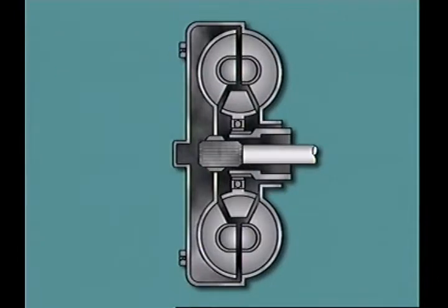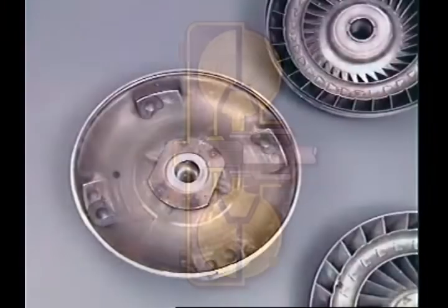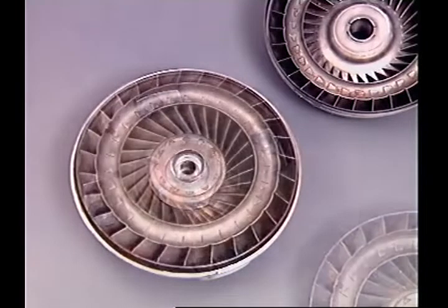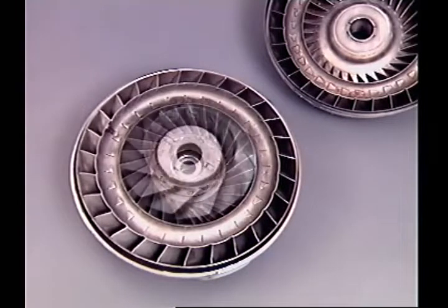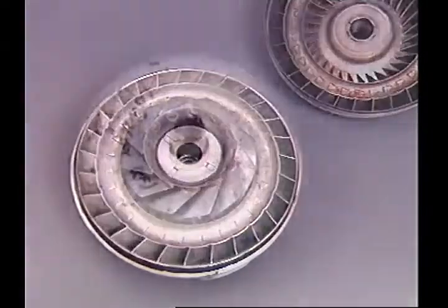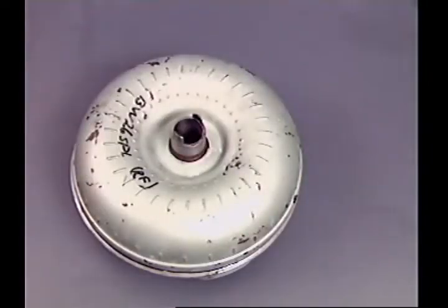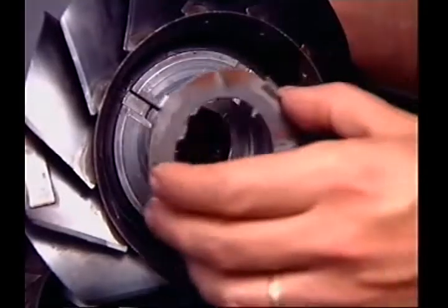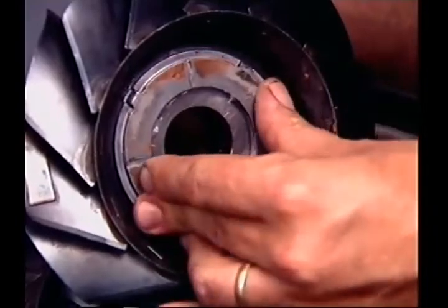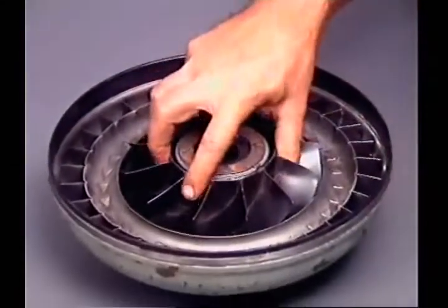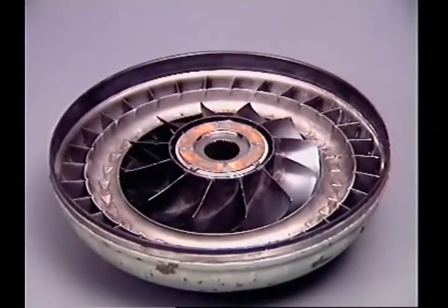In its simplest form, a single-stage torque converter has three elements: the impeller, the turbine, and stator. All three have angled or curved vanes and are contained in a single casing. They are separated from each other by thrust bearings, but maintain a close relationship for efficient torque transmission.